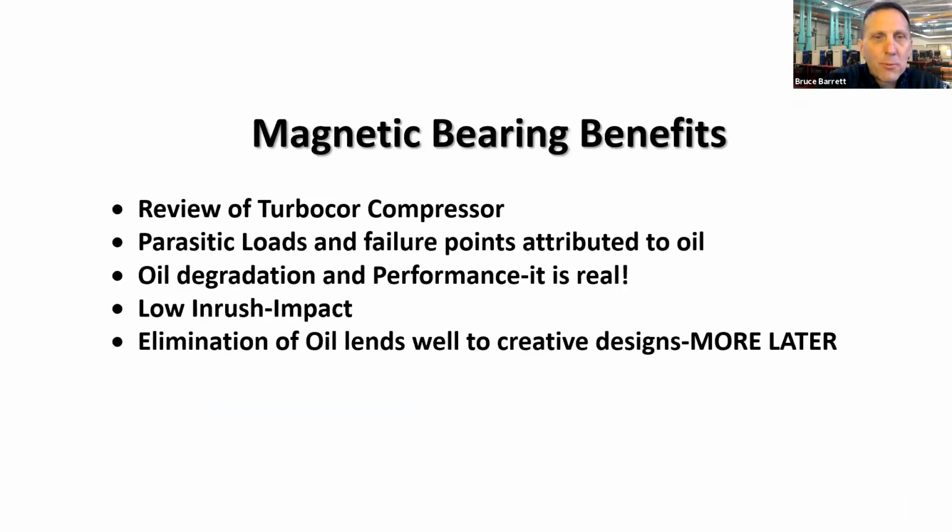Again, this is probably a rehash of what you've heard over the years. Almost every major manufacturer, barring one, offers a magnetic bearing chiller at this moment. It's really becoming the standard. It used to be the exception, and I believe it's more the rule now. When I look at market share results, I believe 80% of the water-cooled market below 1,000 tons is magnetic bearing. So that's a real shift.